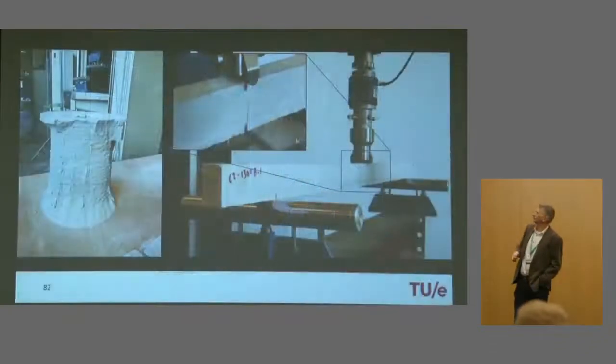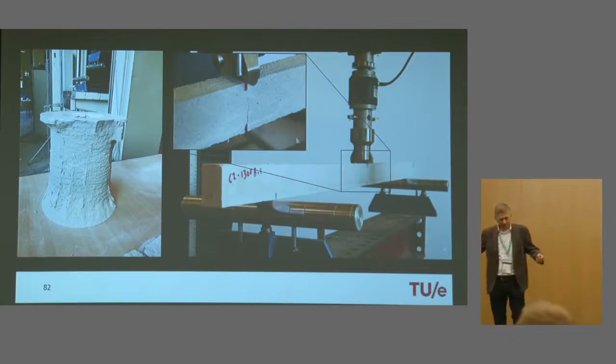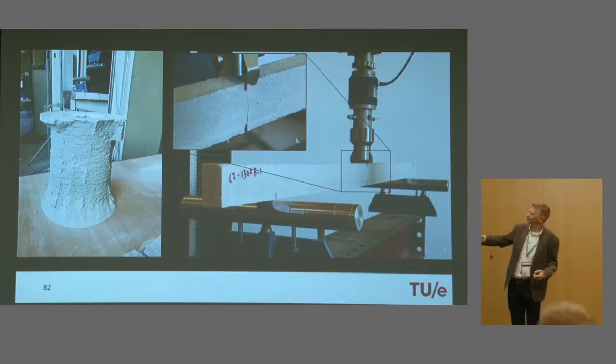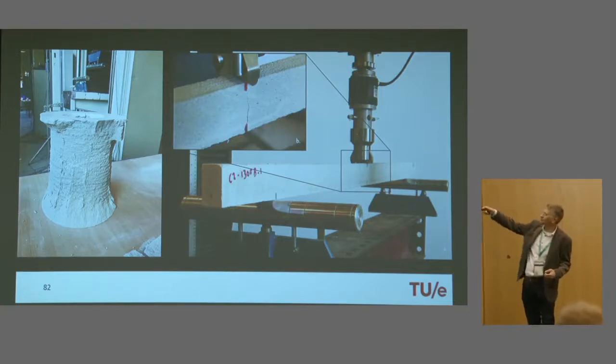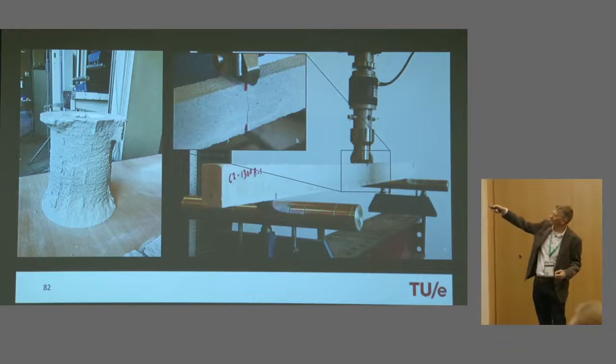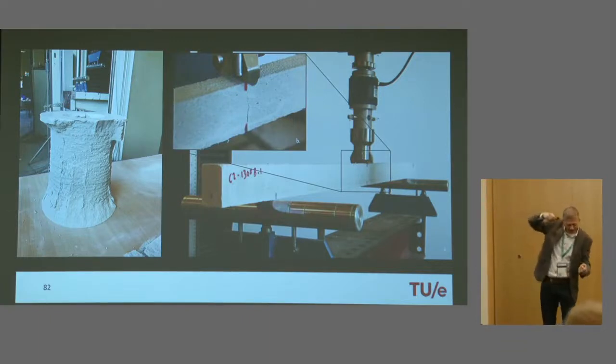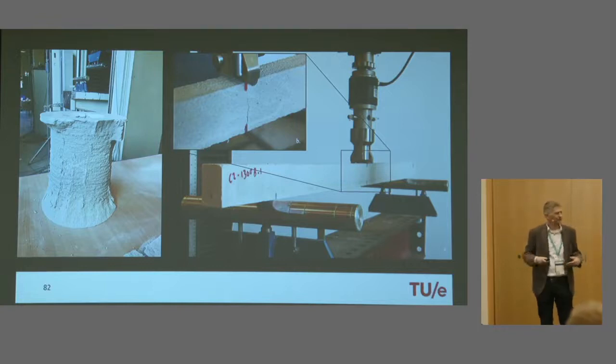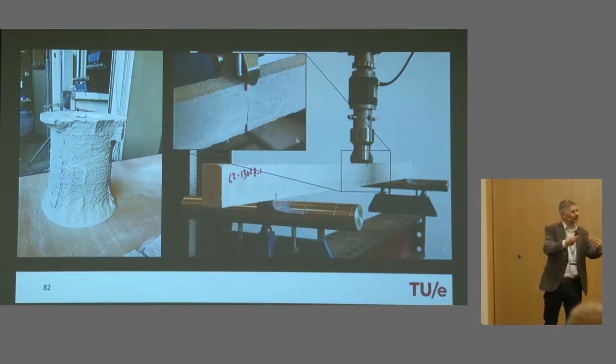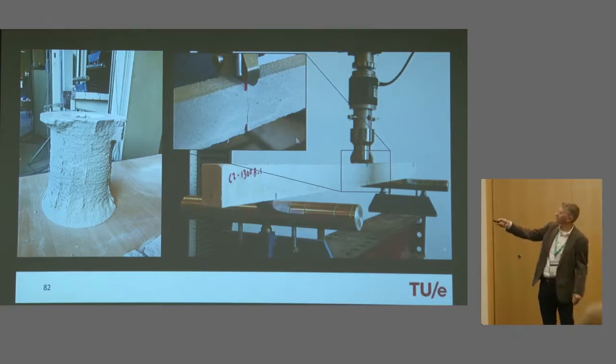So we used that, and with that we made columns like this with the wire that we printed, and then we wanted to use them for reasons of confinement only. So if you compress this, see this as a bridge that is compressed in that direction with a wire surrounding like that. For me it was just confinement. It gives me, as a structural engineer, a bit more safety than if I compress unreinforced concrete, so use that as pre-stressed printed concrete. That wire gives me a nice feeling because everything is embedded and closed within the wire.